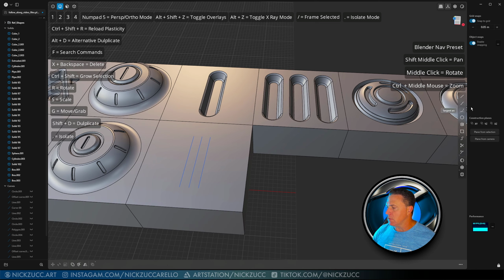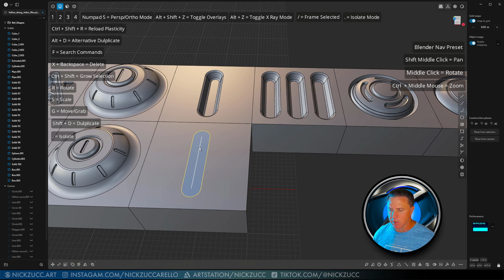We've already looked at this arc tool that exists here. So if we click and drag out, it's at the very bottom, and I can snap here and here like that. Shift R to do my last tool. There we go. Tap 2, and I'll select this, holding down Shift, and then J to join the curves together. So I should make one curve. I don't need this one. I can select it and hide it.